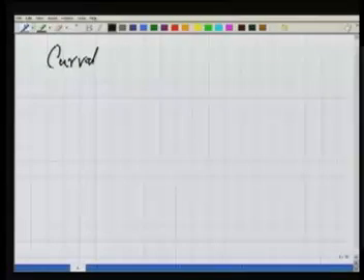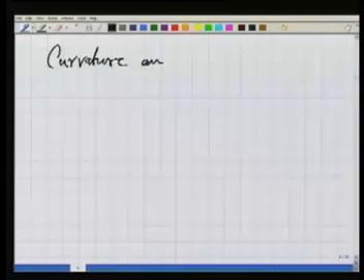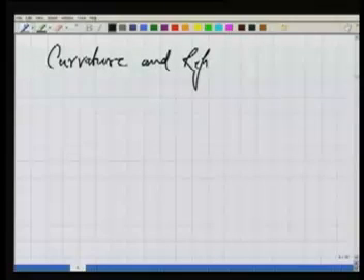So it is advisable that always, whenever we are doing this surveying, we should try to maintain this balance of backsight and foresight. This is important. This is important for one more reason. The reason is, we have seen the effect of curvature and refraction.